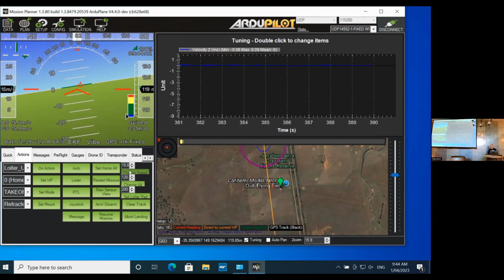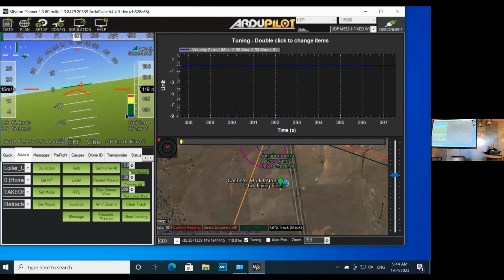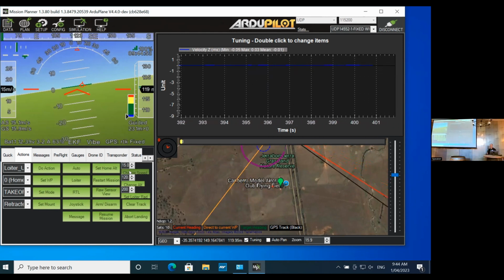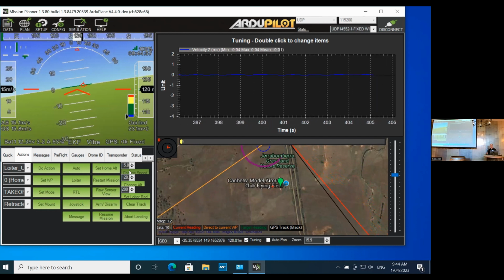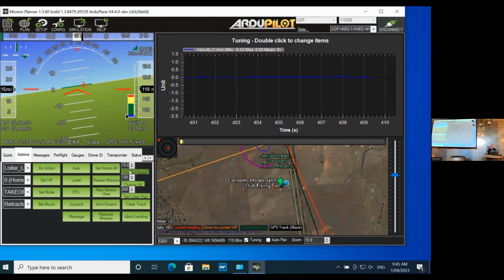And it depends on the aircraft. Low aspect ratio wings are more sensitive to induced drag due to turning. With a high aspect ratio wing, you could be at 30 degrees bank angle and I don't think you would have a measurable effect on the throttle required. Something like a powered sailplane, for example.